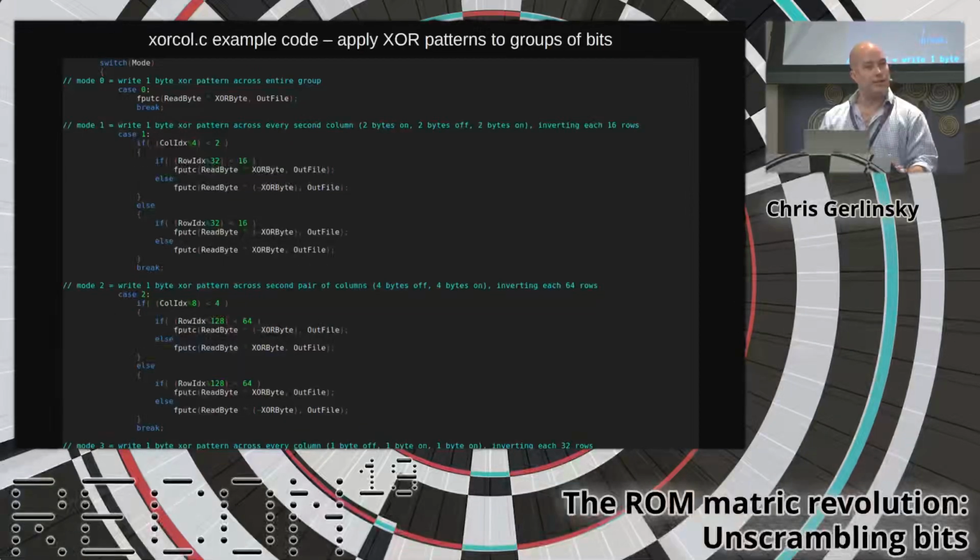I didn't fundamentally understand the scrambling process they were using. I just went column by column and reversed the patterns until I didn't see the scramble pattern anymore, and lined things up to match the bit of plain text that I had. Because the pattern is consistent over the entire ROM, that small piece of plain text allows me to decrypt the rest.